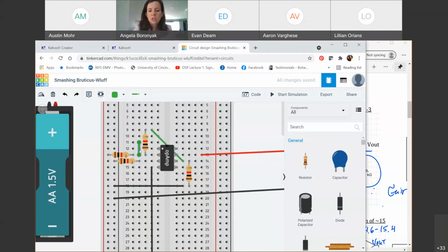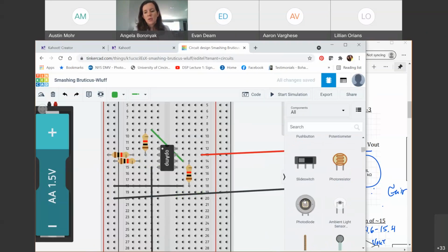Okay, questions or concerns about our first one? Again, you're likely to have either RF or RN be a combination of resistors, not a single one here. And you need to calculate what they should be to get a gain of -3. There are multiple possible answers for how to do this. I don't limit you to just one. You want to then measure the voltage drop across every resistor in your circuit. Okay, so remember, take your multimeter.